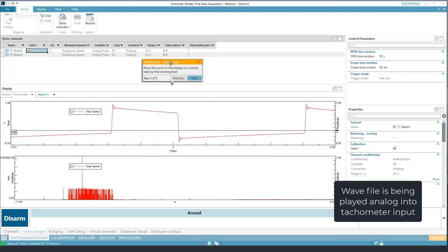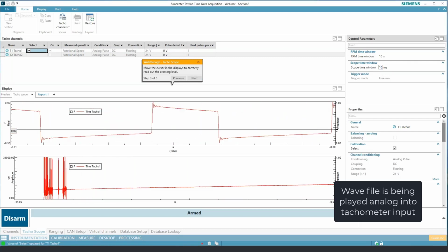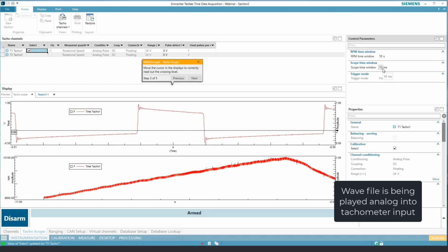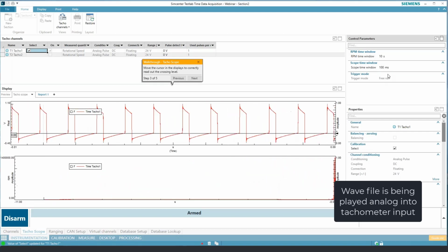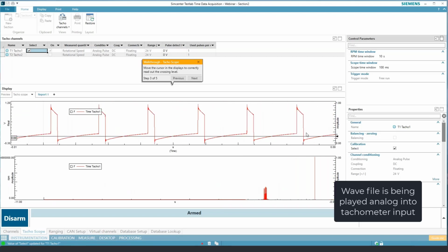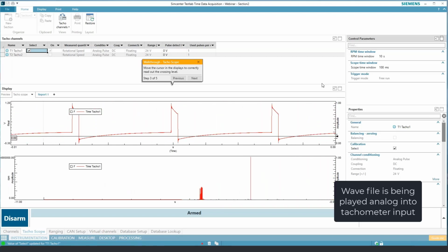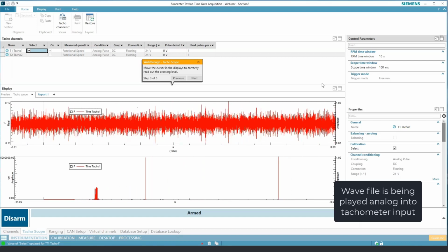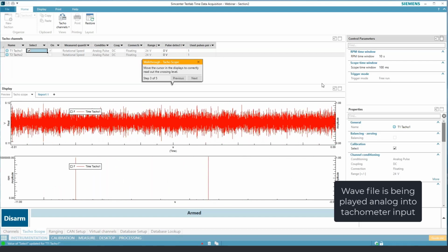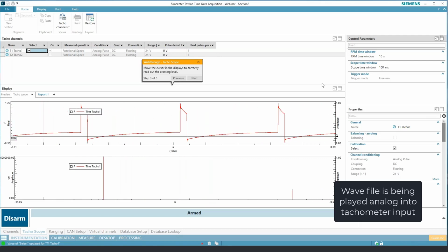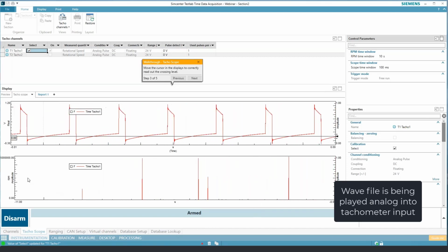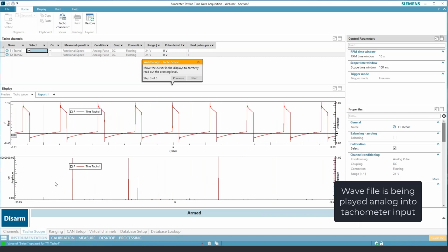So the first thing I'm going to do is deviate from the script here of guide me and increase my scope time window from 10 milliseconds to 100 milliseconds, so I get to see some more realistic pulses, both at low speed now and at the higher speed. And what I want to illustrate also, in addition to the pulse train, here we are in the wave file cycling back. Here's my pulses back. As the RPM increases, what I want to illustrate is the RPM value being calculated on the bottom.